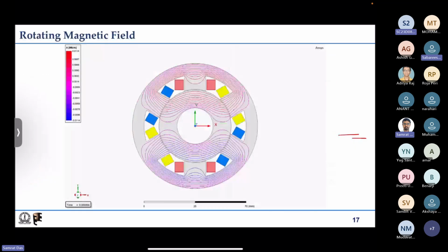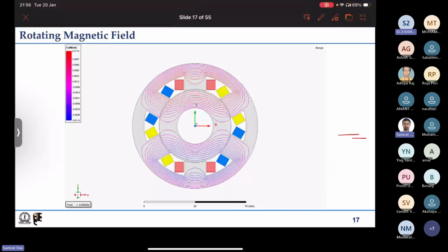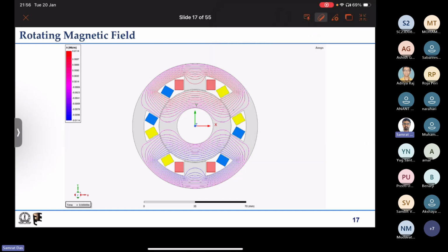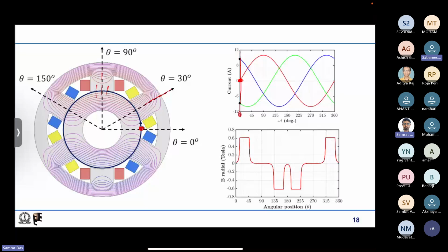One more question here. Something like above 3 phases, a 6 phase machine, how can it be realized? Only through an inverter or some power system? Only through an inverter. If you make your own power system with 6 phases, then you can locally feed your own machine. But otherwise, we do not have a 6 phase connection anywhere. Yes, only through an inverter.